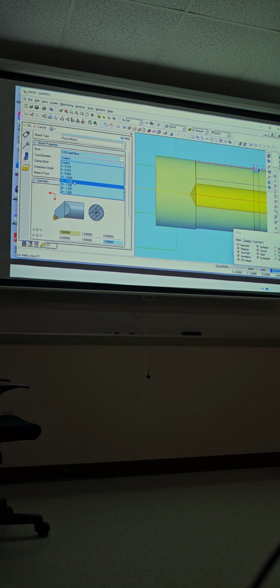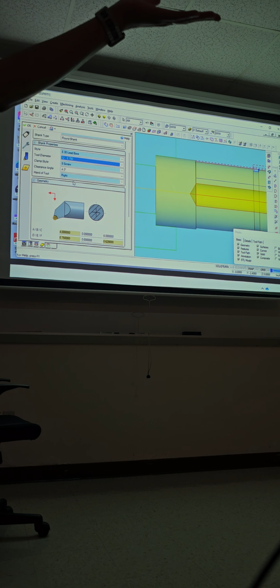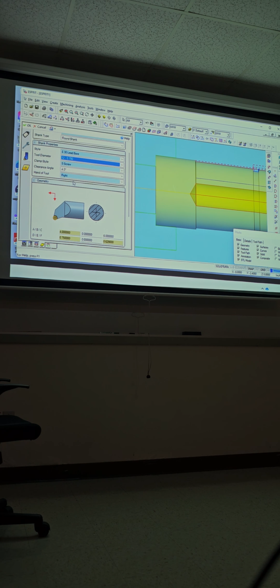So to go in there, I can now go 1.5 inches. Maybe let's go at least a 1/4 inch smaller. So we're gonna go a 750 boring bar diameter. That way it can fit within that 1 inch diameter hole, because remember, it's gonna start cutting, and while it's cutting, it's gonna make the hole bigger. If your hole right now is 1 inch, let's keep it a 1/4 inch smaller. So if it was 2 inches, what is the size of your boring bar? You can go 1 inch. But in this case, 1 inch is the hole, so you can go 3/4, because you don't want to go with a bitty boring bar because it's too fragile.